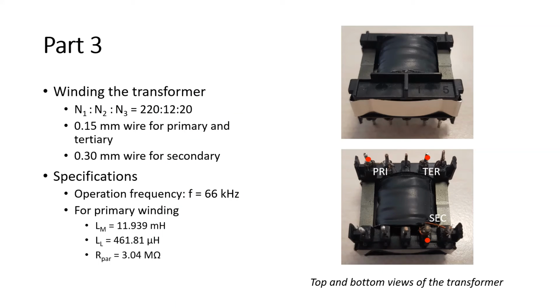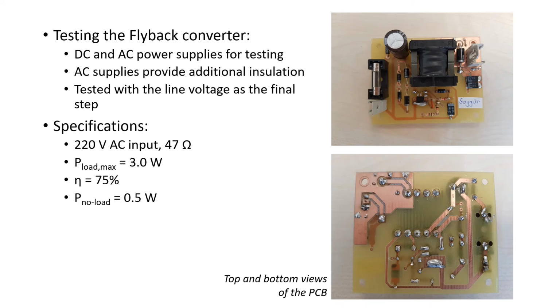In the third part, I began by winding my transformer and running tests on it using the RLC meter. Then I soldered all components on my PCB and completed my flyback converter and ran tests on it using the DC and AC power supplies.